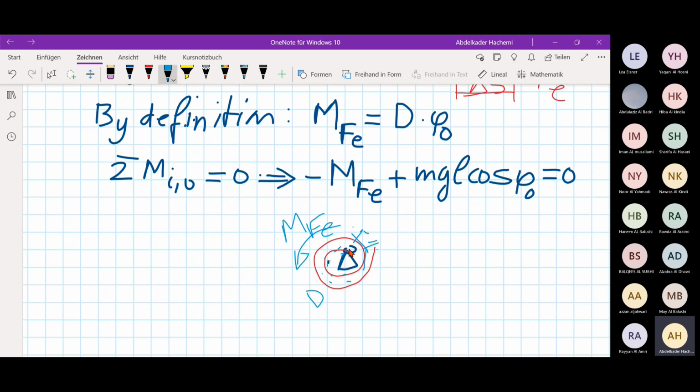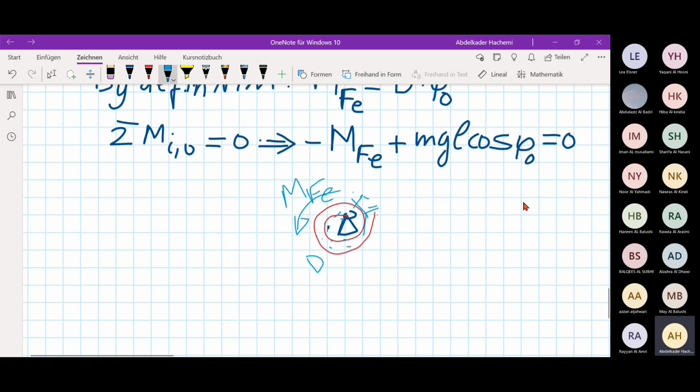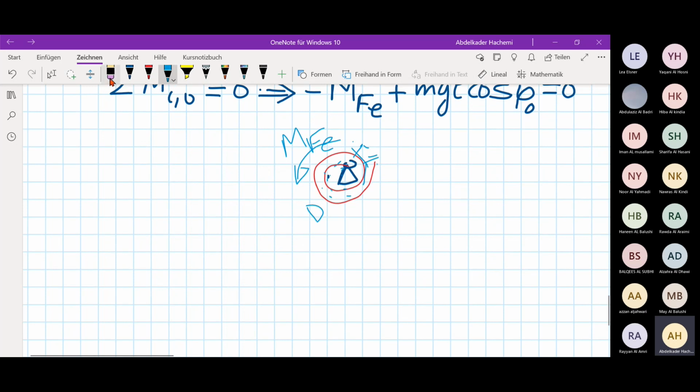What we have as external forces, the rod is massless, so there is no force from it, and we have only the particle which has the mass. Okay, then it means here at phi 0, we have the weight. We make the projection of the weight mg. Yeah, the arm is only L cosine phi 0. Okay, this is the moment. It's always the force multiplied by the arm. Now, if we do so, then we get here